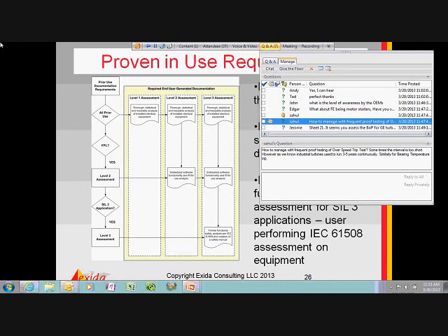Here's a question from Sahul. How do you manage frequent proof testing of overspeed trip tests? Okay, so I would say the most I've seen people plan would be once a year. But the question is that sometimes industrial turbines run 3 to 5 years continuously, similarly for the varying temperature trip.